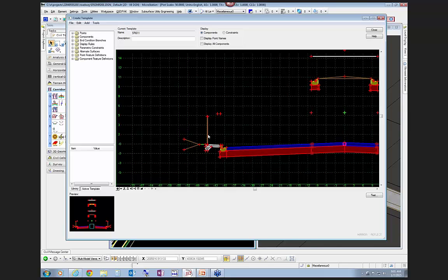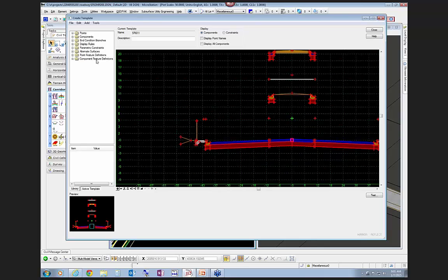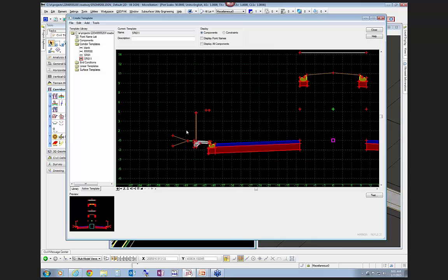When you have variable outside conditions, there's really three ways that you can handle them, maybe even more than that. You could build separate templates. You could copy this particular template and essentially scratch out this type of end condition. Maybe you had to put a shoulder in here with a ditch and tie back to the right-of-way line for a portion of your corridor. I wouldn't recommend creating multiple templates that just have varying end conditions.